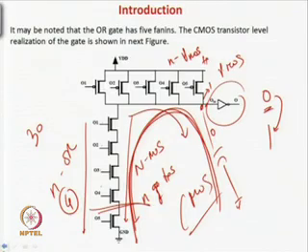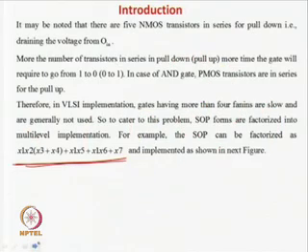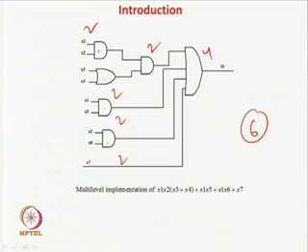But in this case, if you check the number of fan-ins, it is 3 over here, 3 over here, and in this case it is 4 over here. So, the fan-ins of the gates are higher in this case. That is why, if you just take the ad hoc manner, that wherever you find a gate with more fan-ins you break it, it will consume much more area, rather than if you go for this type of factorized implementation, where you have much fewer fan-ins.